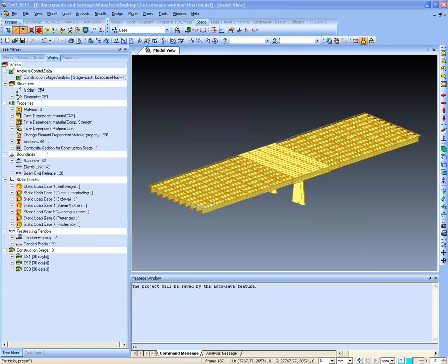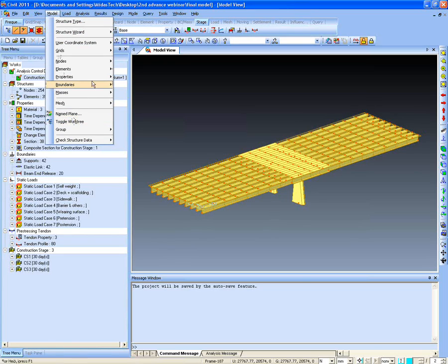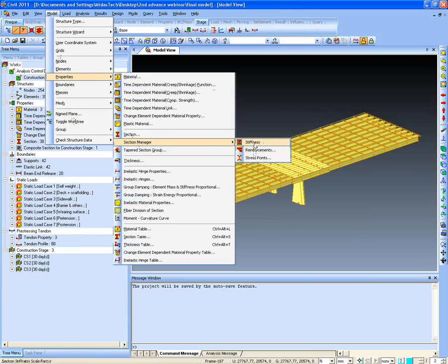There is a question by Mr. Eddie, that he wants to do the FRP strengthening of the beam and how he can model it in Midas Civil. So as I told you in my presentation, you can use the section stiffness scale factor.